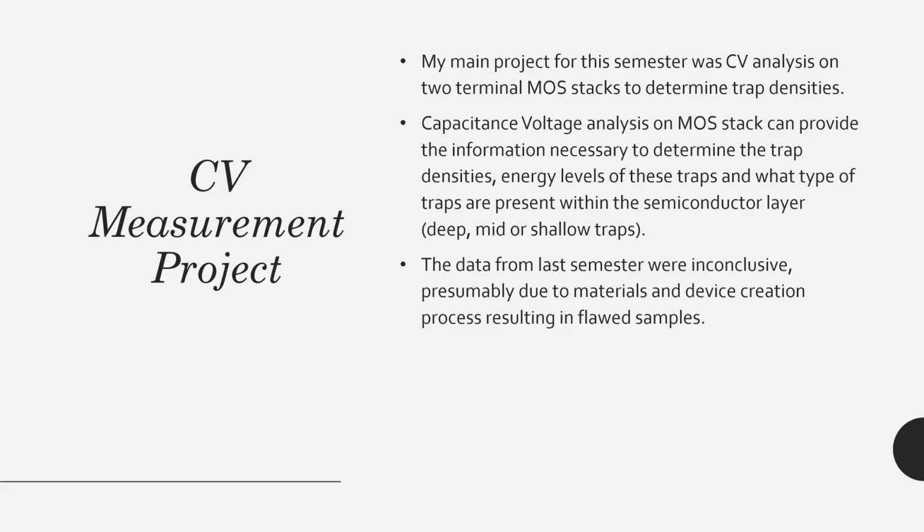Capacitance voltage analysis on MOS stacks can provide the information necessary to determine the trap densities, energy levels of these traps, and what types of traps are present within the semiconductor layer. The data from last semester were inconclusive, probably due to materials and device creation processes resulting in flawed samples.